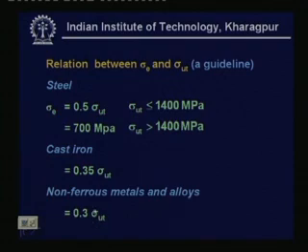Well, sometimes there is a variation over here; it can come to something around 25% to 30% also. As a matter of fact, this depends on the material, and again the handbooks can provide you with some guidance for considering the endurance limit of a material, provided the ultimate strength of that particular material is known to you.